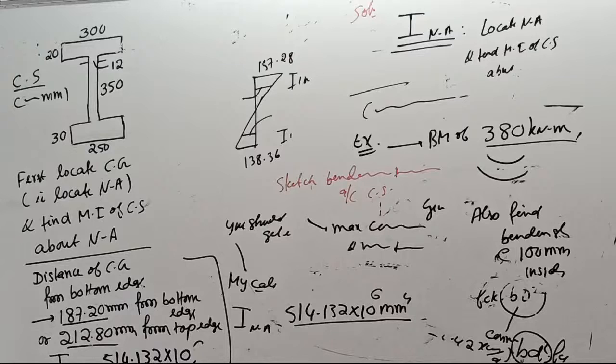Yes, bending stress and RCC are directly connected. See, there also the same thing you are doing. For a given BM, you find the stress developed. Or you decide what is the balanced section and under reinforced, over reinforced. Then you put the permissible stress. Then you get MR. Correct? They are directly linked. All this in the RCC class I told you, if you remember.